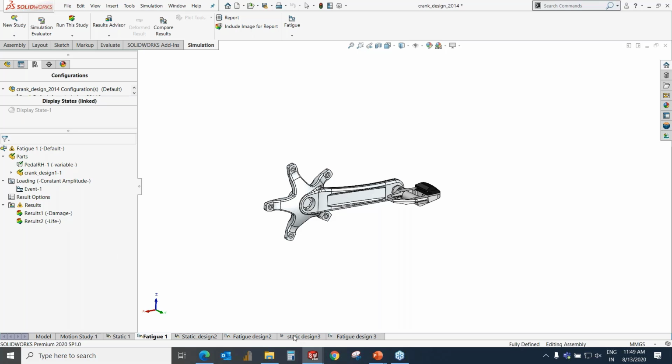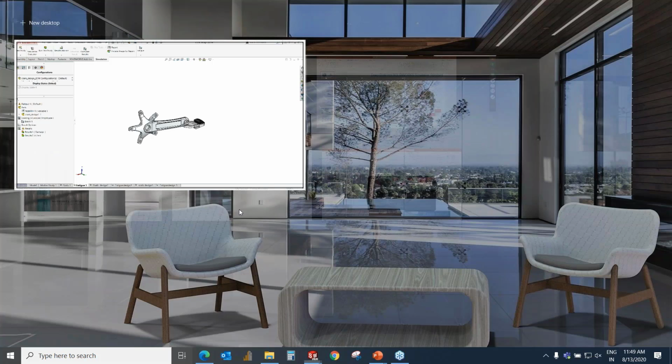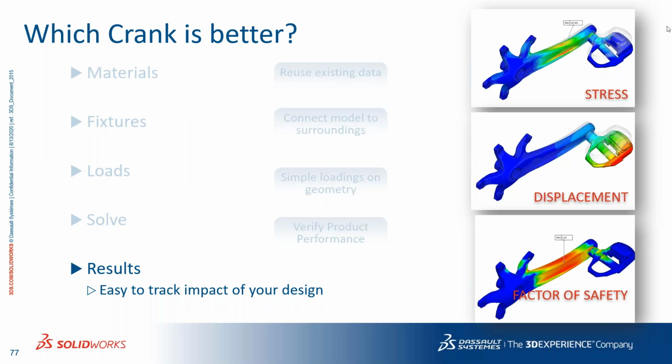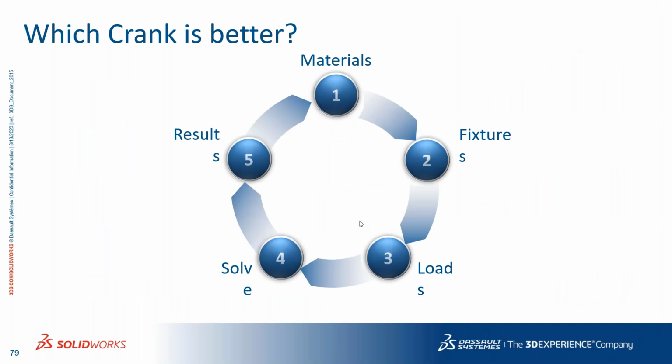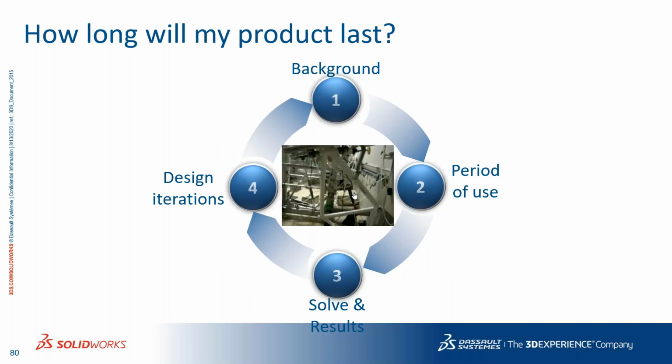I have carried this out for different designs also. Let me compare the results here in this PPT due to the time constraint. You can identify displacement, stress, and factor of safety. Once that is done, I will go for the fatigue analysis. See, this is how it is performed. Otherwise, I have to completely apply the load and test it in the experimental setup, which will be a very difficult task.